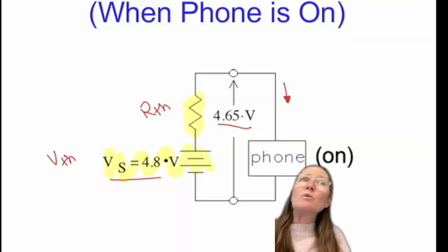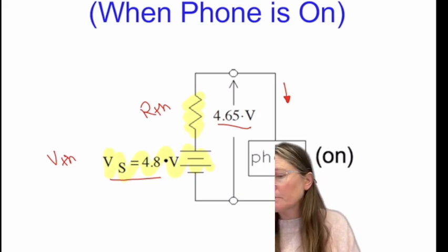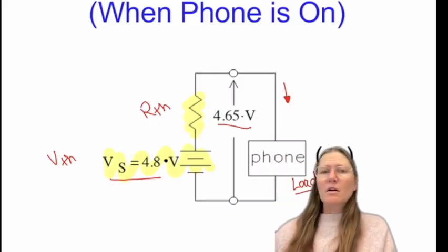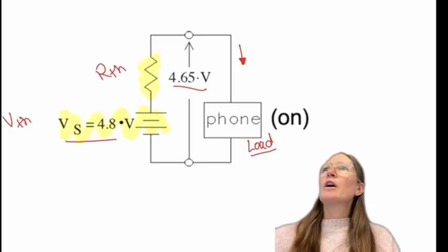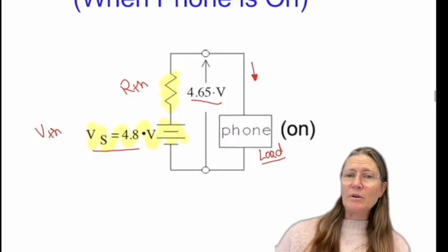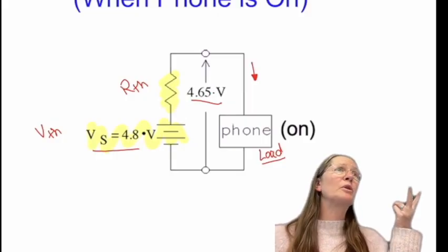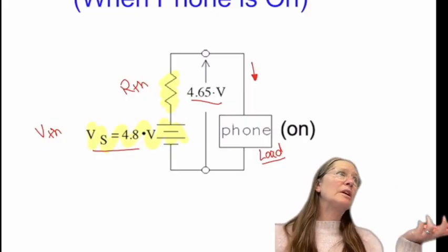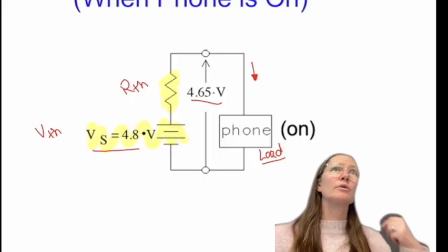So that's usually what we want to know from a complicated circuit: what if we put on what we call a load, how does the current and the voltage change? And so we're going to learn this technique called the Thévenin equivalent technique to be able to reduce that complicated circuit into these two components. So when we talk about getting a Thévenin for a circuit, we're looking for these two components, resistor and voltage.